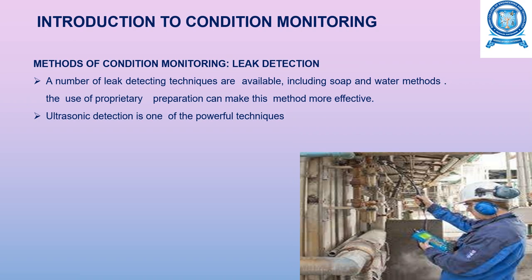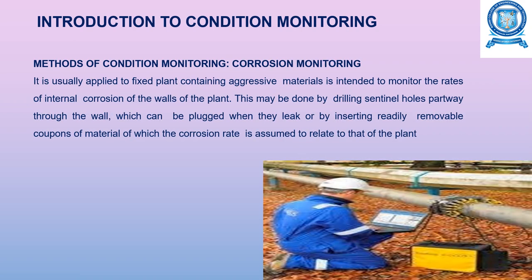And the next method is leak detection. Here you have a number of detection techniques, including soap and water methods, and the use of proprietary preparations can make this method more effective. And here you can use ultrasonic detection, which is a very powerful technique for leak detection.